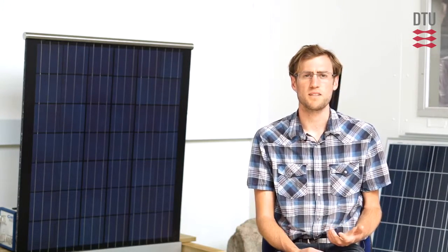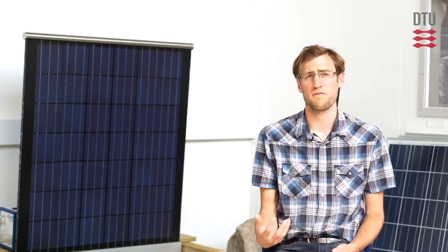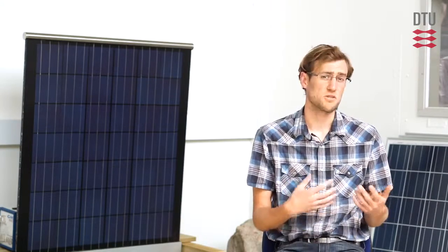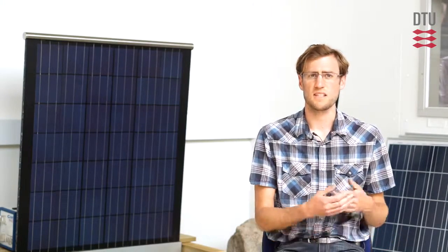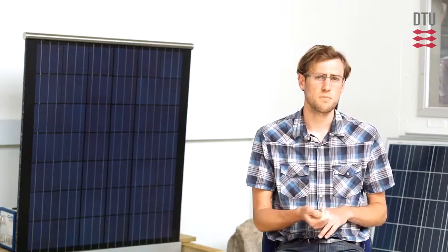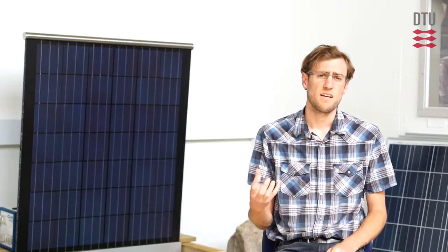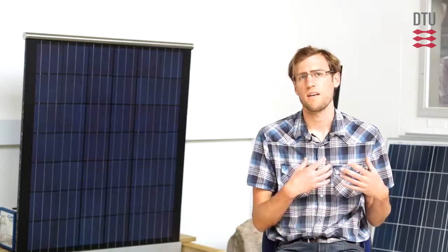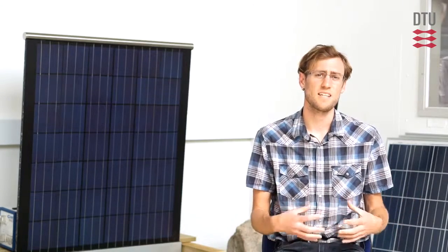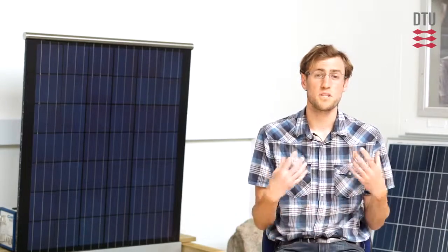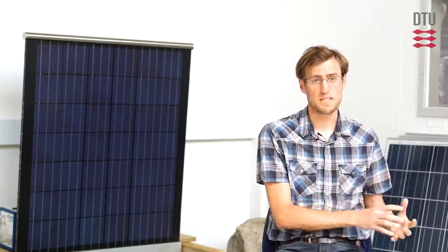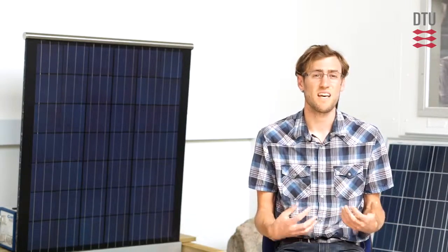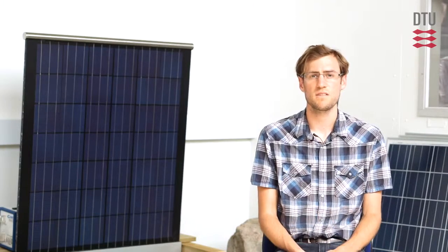useful in performance modeling. For example, if I have a weather file that describes a location's typical meteorological year, they say. And that would include things like the average sun intensity, average temperatures, wind speeds. If I have that and I have an IV curve that can be explained by a one diode model, I can put those data together to start making production estimates for a basic PV device in a given location, and I can model what's the expected energy yield in that location.